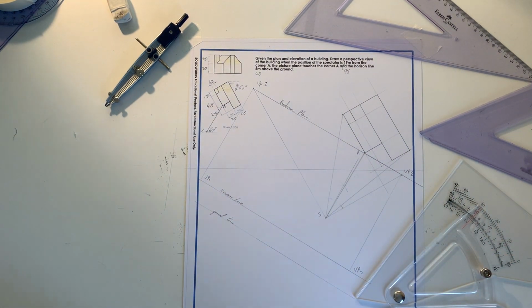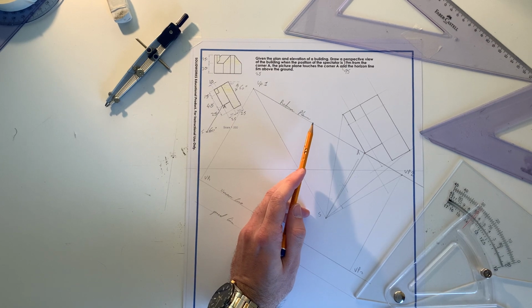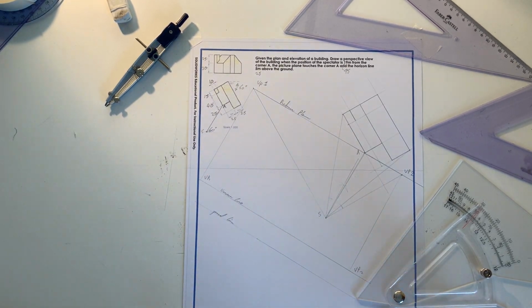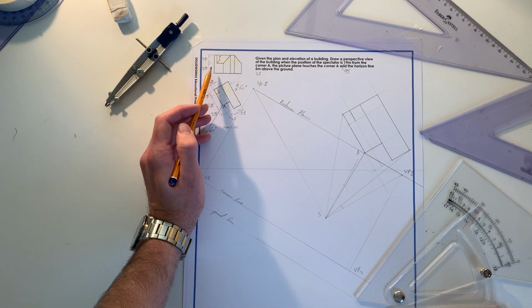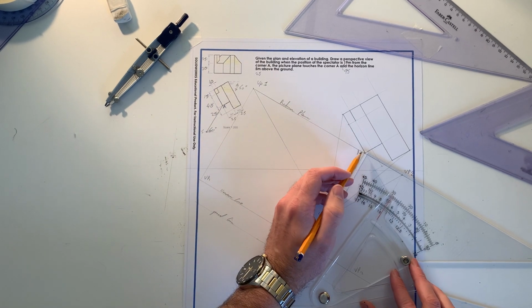Now what I can start doing is drawing in my object itself. Now the one thing that I know here, the only true length that I'm going to have is the line or the corner that's basically sitting perfectly on this ground line itself. And that will only be any line or any point that is on the picture plane. And that is A. So I can take down A and take my measurements above here and slot them in, which are going to help me finish off the drawing itself.